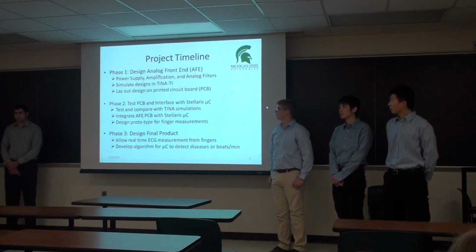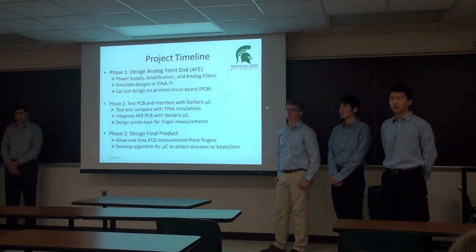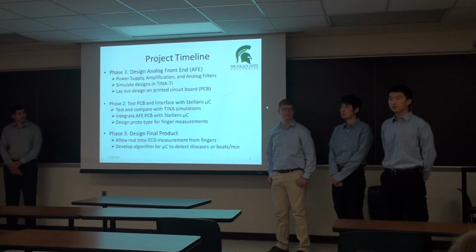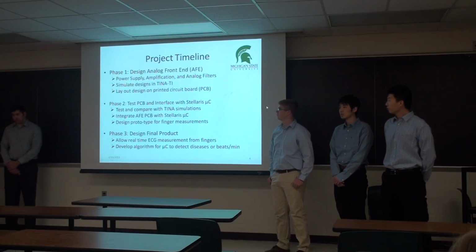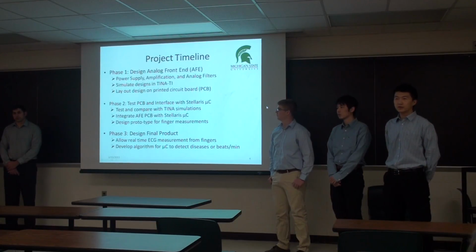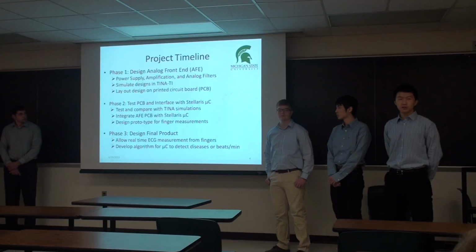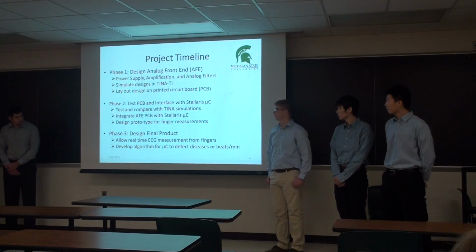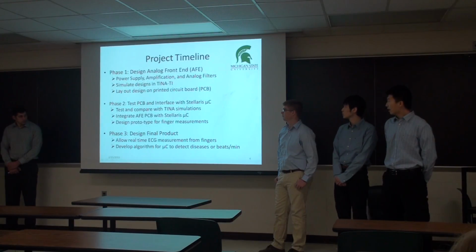First of all, we are going to test and compare our cardio simulators from TI, which is our input, to see what the cardiac signals look like and how much noise they have. And then we are going to integrate our PCB board with the simulators and the Stellaris microcontrollers to test the overall project. And this is pretty much our project, but we still have a phase 3, which is to design our final product.